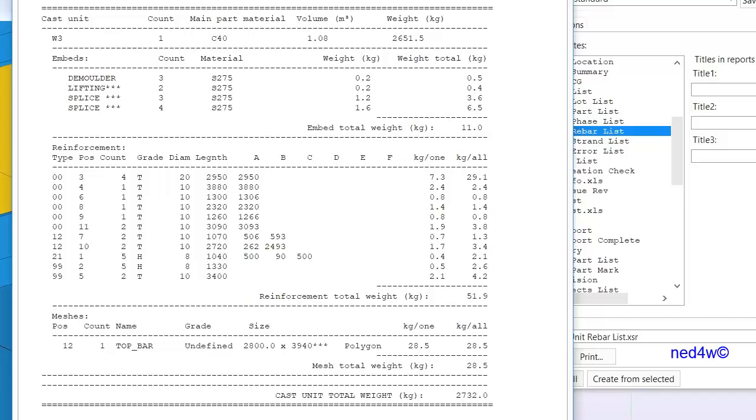After that, the reinforcement will show you the different reinforcement, the position number, and the length. So 40-20, remember the dowel bar, 40-20, and then you have the 10 dia bar for the trimmer bar, and 8 for the loop, the connection, and so on.